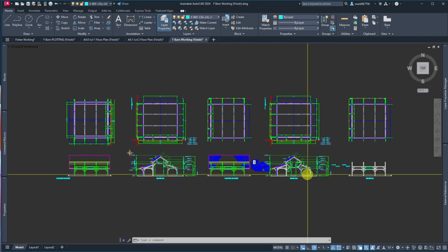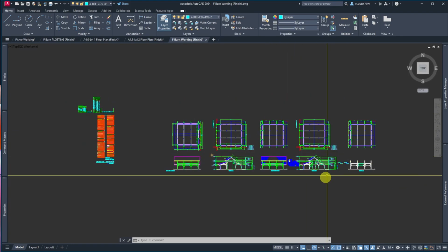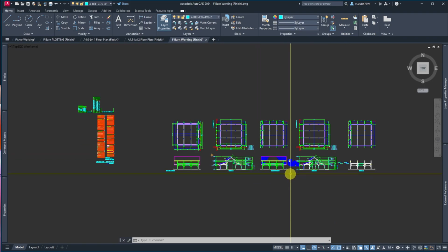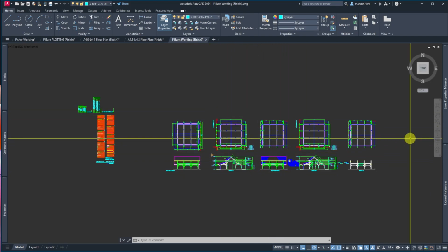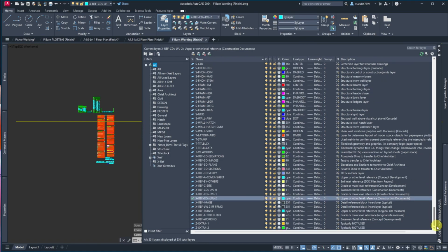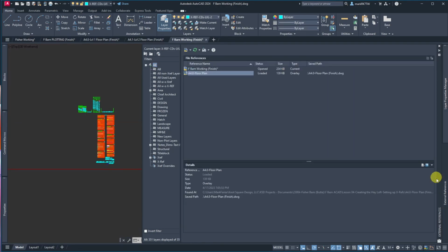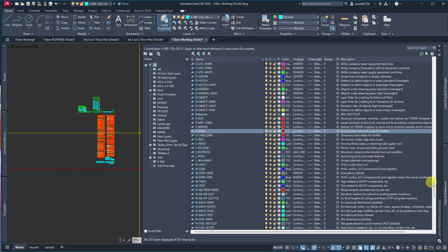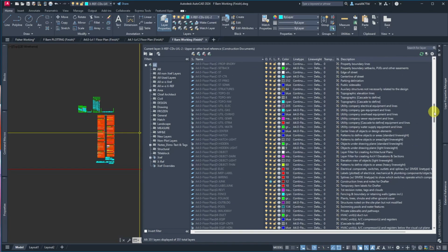Oh, it is going to be kind of different, because to do the rear, I want to rotate this all the way around. So I'm going to do them to the side. One thing I can do is these are grouped. This is with this, and this is with this. So before I really move big stuff, I'm going to go to all my layers and check that everything is on and thawed. I'm looking for a light and a freeze, because I don't want to leave something behind. Like that cloud was in a certain place, and if I move the building, the revision cloud would have been left behind, and I'd be wondering what it was. This is an XREF. Whether I move this or not doesn't make any difference.